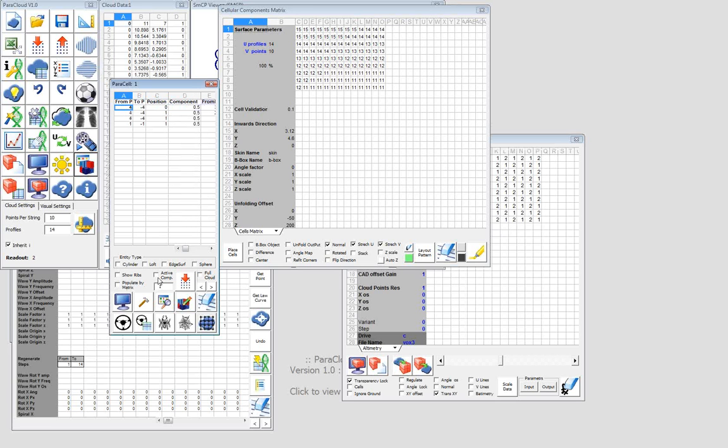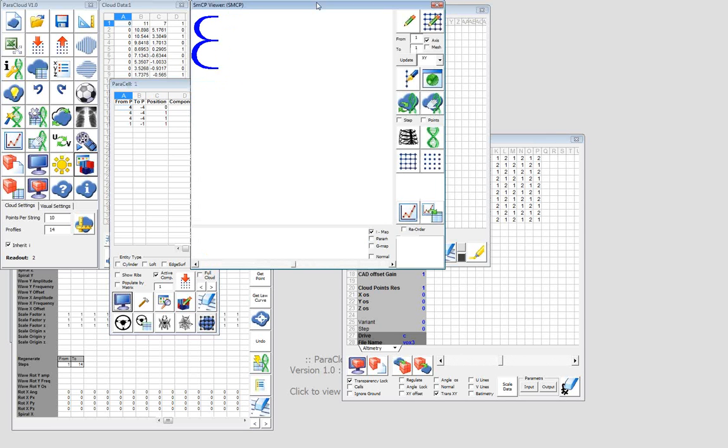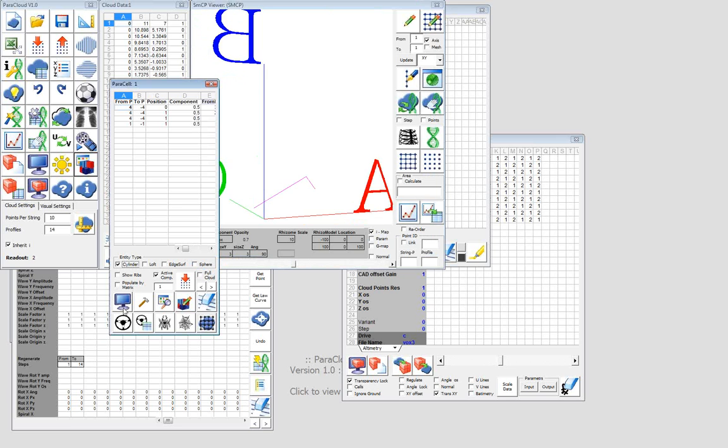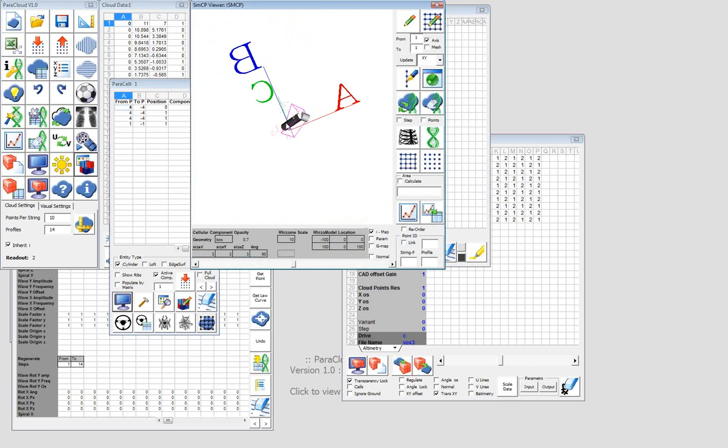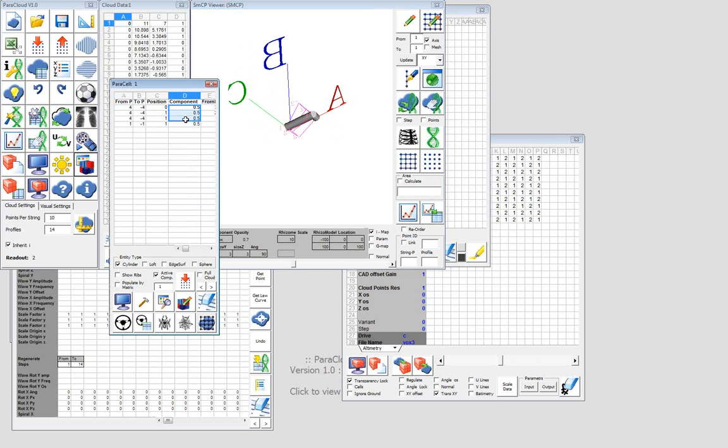We can preview this active component and see how it looks as a cylinder. So we can see how it resides on the first population cell. And we can control here the radius of that cylinder. So let's say that we wanted to have this bit that connects to the surface very small, so we'll move this to 0.1. And we wanted the main diagonal to be, let's say, 0.3. And I'm going to use on the other diagonal 0.3 as well.